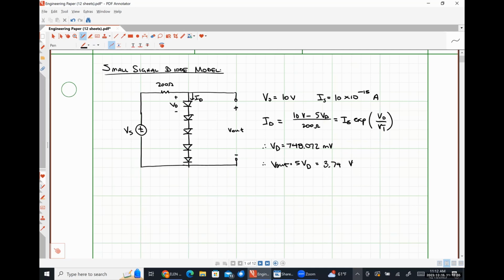What do you mean by the diodes have a resistance? For metal semiconductor junctions, we had an equation for resistance effectively for ohmic contact, but these are rectifying contacts. The reason why I'm being elusive is because we're literally going to talk about diode resistance here in a moment, but it's not a large signal quantity, and we are dealing with a large signal circuit.